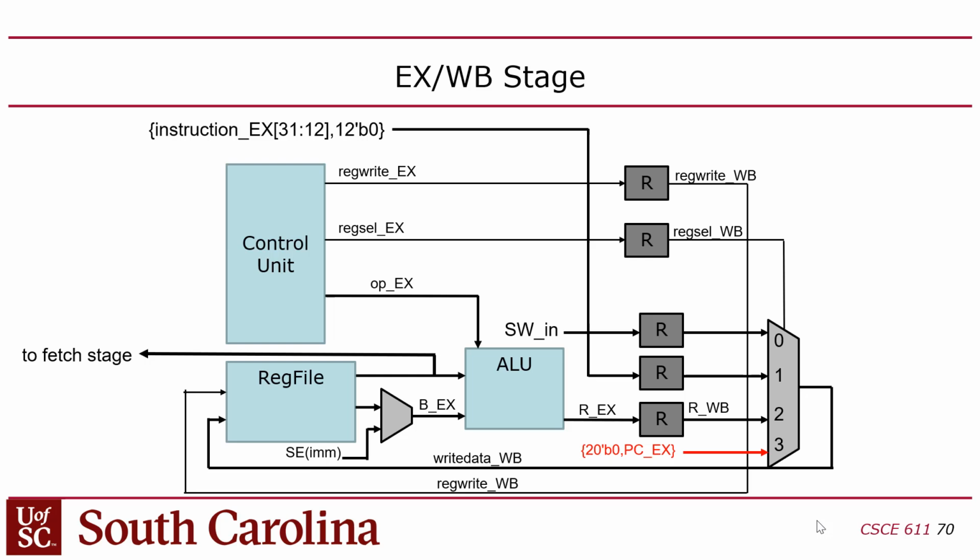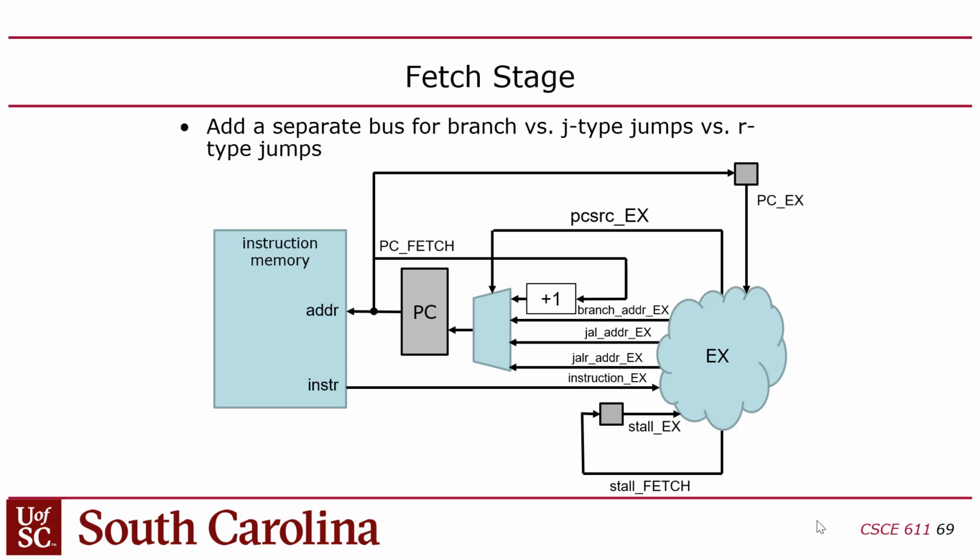So what that really means is that the stall signal is actually linked to the program counter source. The program counter source is determining where you go next. Under normal circumstances with no change of control, PC source is 0, right? And if PC source is 1, 2, or 3, that means you're taking a branch or a jump, which means that the stall signal is essentially just saying, if PC source isn't 0, then stall, right?